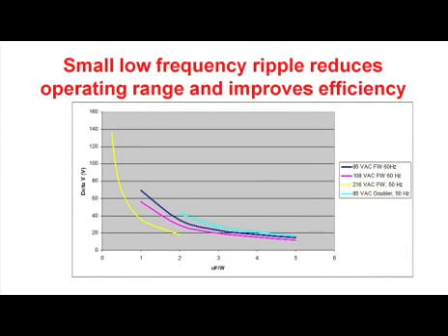So I've done a couple simple charts here to show the impact of the value of the capacitance versus the minimum range that you have to operate over, or basically the change in voltage on that cap at several different line conditions. What I've done is I have normalized the value of the capacitance by the output power of the power supply. For instance, if you had a 5 microfarad input cap and you're only putting 1 watt out of the power supply, you would end up over here on the curve on 5.